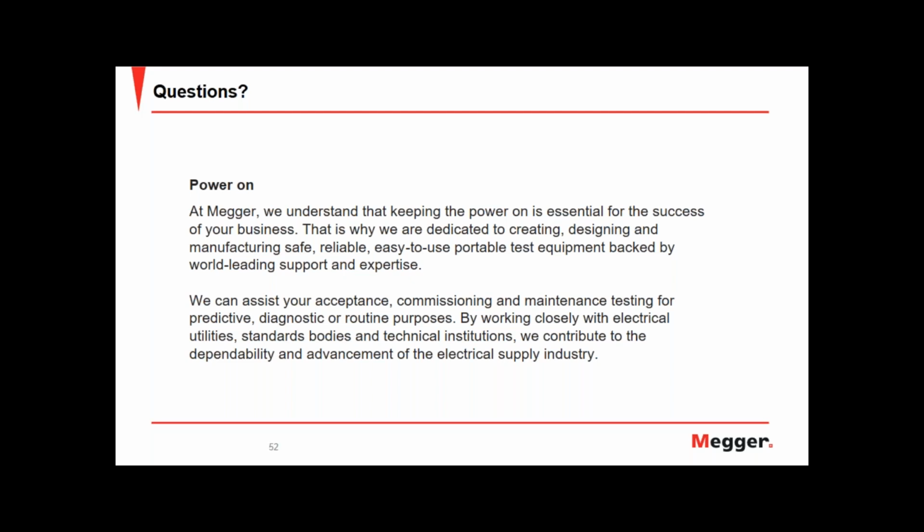For other equipment like oil immersed transformers, well, those are not that common to get moisture inside that easy. But if they have moisture, of course, that has to be determined previously with other advanced testing methods. And then those go through a different dry out process, more cumbersome, more complicated, because now you have to extract the moisture from the cellulose, which is immersed in oil. So it's a different method.